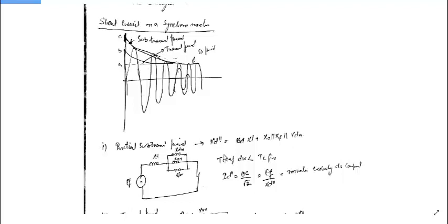So in the earlier period, you can see the envelope of this current is very high. It will draw current through the damper winding as well as the field winding, so that the total current will increase. When the damper winding and field winding currents increase, the total flux will increase, and it will try to make the flux equal to the actual flux. So that is why you will see that currents will flow through the damper windings and field windings, resulting in the increase in flux. You will see the envelope of the current will be more.